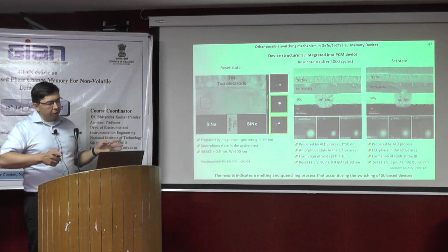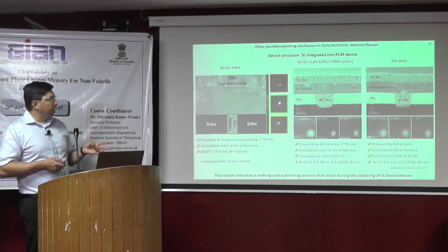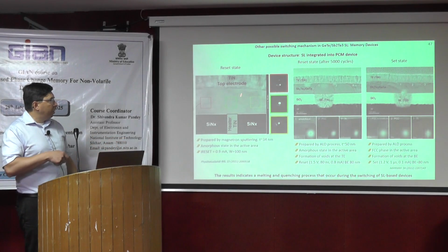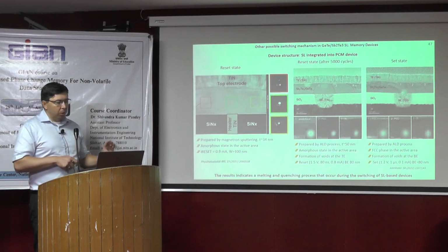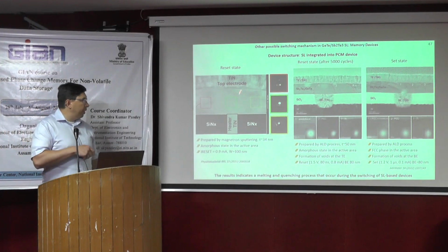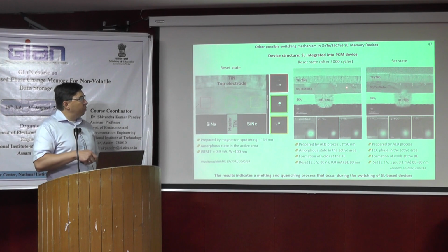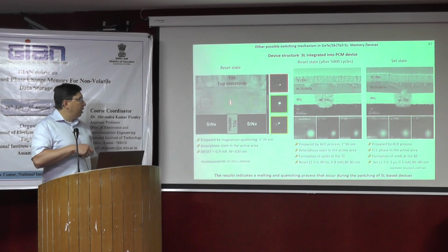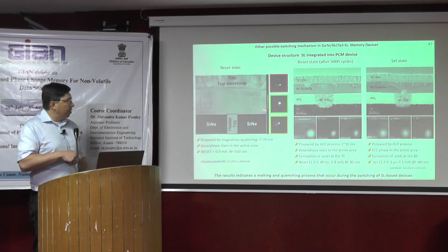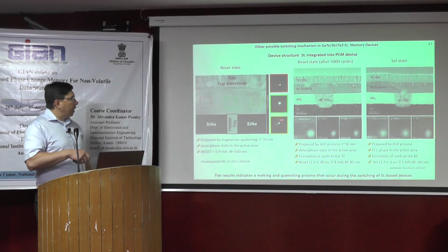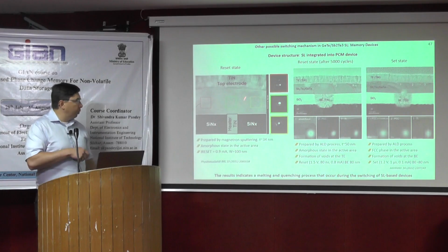The only difference from the single phase material is that we still have some crystalline GST or superlattice, which has very low thermal conductivity, even lower than the FCC phase, and maybe this could be the reason for the lower reset times, that the energy can dissipate much faster to the sides of the working device.